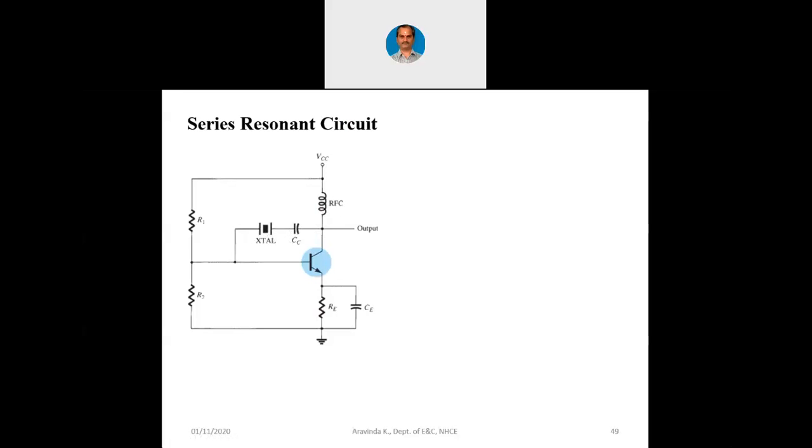You have to visualize the equivalent circuit now. To the equivalent circuit, there is one more capacitance connected in series now. We want to have a series resonance predominantly. That is why we can use this coupling capacitance here, this CC, in series with the crystal, so that the parallel resonant counterpart of the crystal can be completely ignored that way. It need not be functional that way.